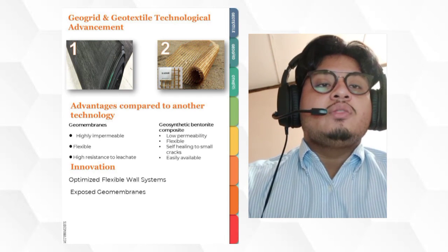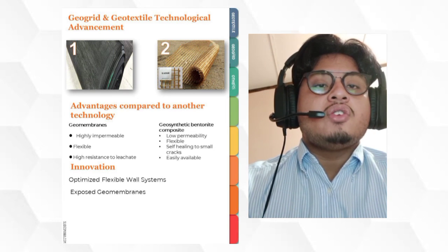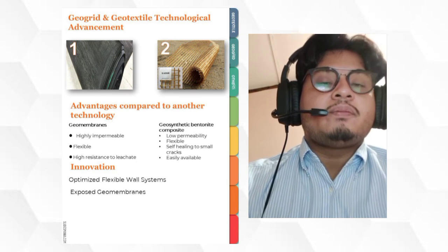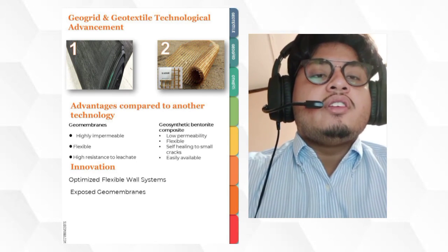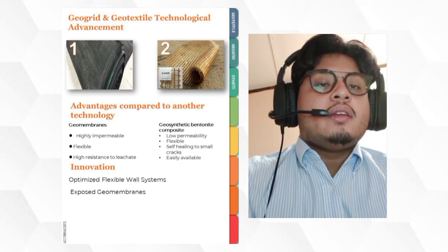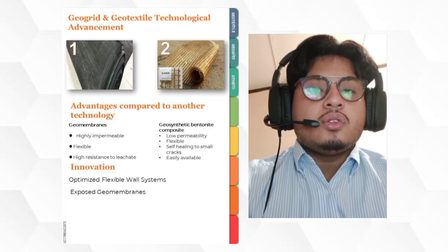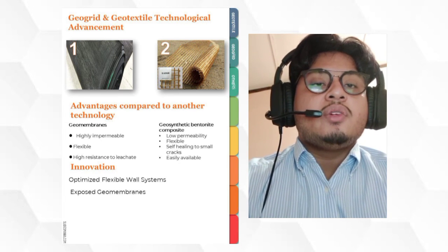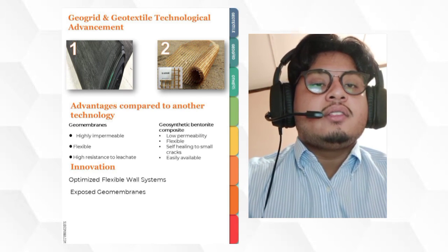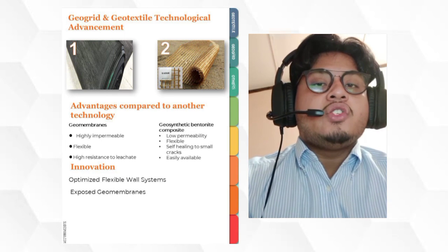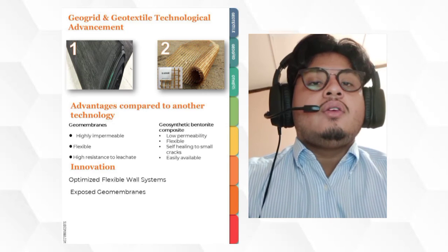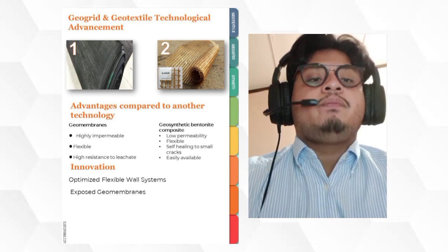Key aspects in the design of exposed geomembrane covers are the assessment of the geomembrane stresses induced by wind uplift and the anchorage requirements against wind action. Wind uplift of the geomembrane is a function of the mechanical properties of the geomembrane, the landfill slope geometry, and the design wind velocity. Also, wind uplift design considerations involve assessment of the maximum wind velocity that an exposed geomembrane can withstand, of the required thickness of a protective layer that would prevent the geomembrane from being uplifted, of the tension and strain induced in the geomembrane by wind loads, and of the geometry of the uplifted geomembrane.